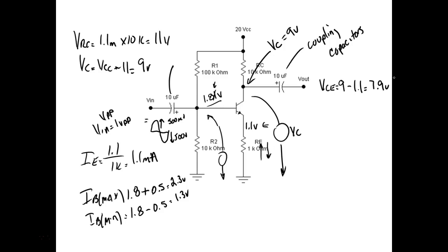And then once you got it, then of course, you realize that every circuit is not going to be exactly the same, and you make sure when you set up the specifications, it works within the tolerance of all your devices. So your amplifier might get a little bit out than the next person, right? So that means I might rate my amplifier at 50 watts, but sometimes it might give me 75. Sometimes, and the worst case might be 60. Well, I would rate it at 50, which means that would make sure my amplifier gives me what everybody expects out of it.